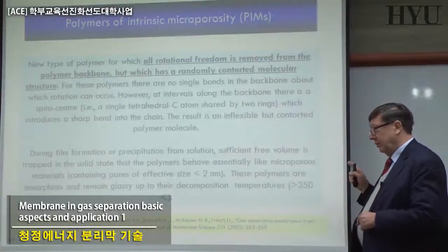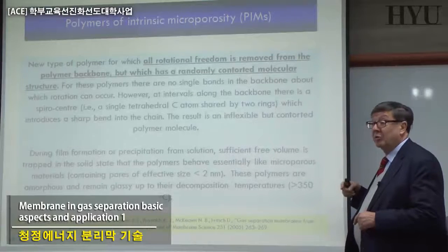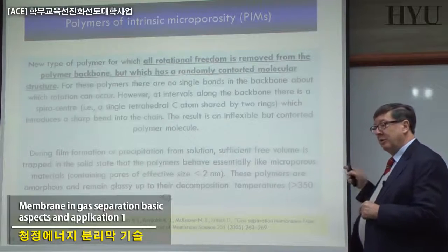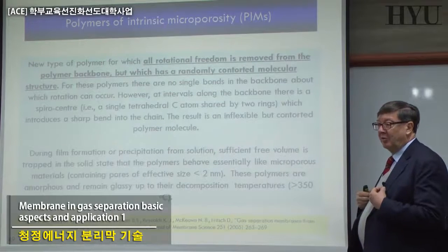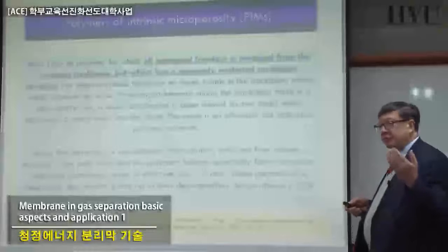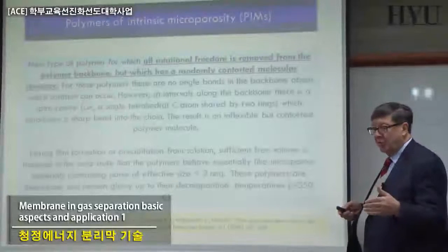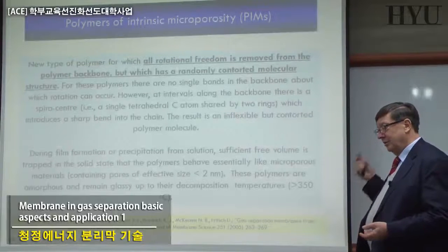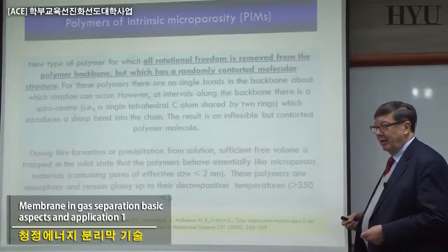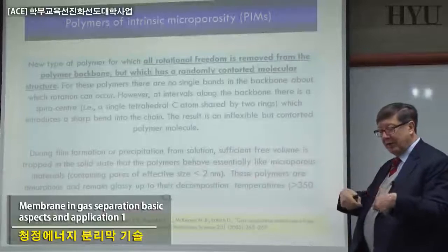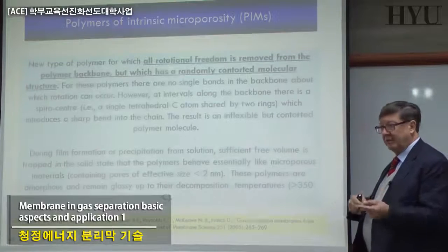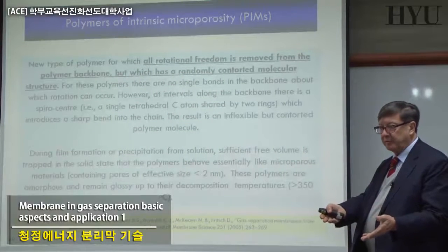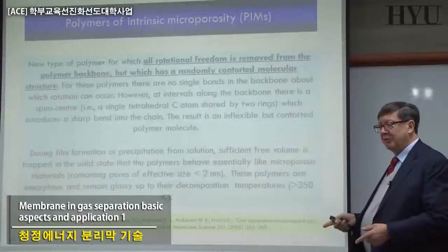Keep in mind that this approach is quite interesting and also successful, because people sometimes don't remember that this approach has already been utilized also in reverse osmosis. The first traditional reverse osmosis membrane in cellulose acetate, if you go in the literature of the 70s, you will see that when you prepare cellulose acetate by diacetate, triacetate, etc., after casting your membranes at room temperature, you always make a thermal treatment.